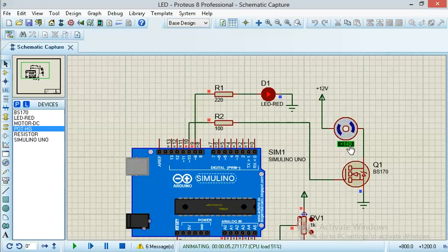Okay, we are reaching some stable figure, 150, 151. Now let's drop the value of this potentiometer by clicking this down arrow, and let's click and hold. By that we are reducing the value of the potentiometer. So your LED is beginning to dim.